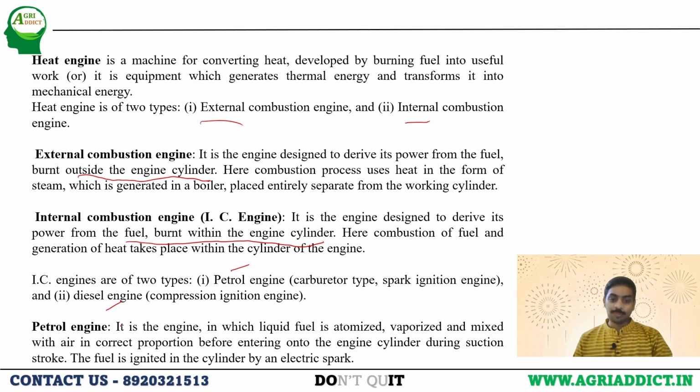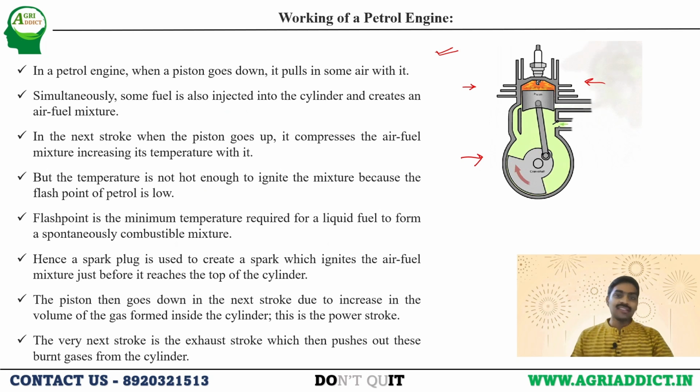And now first talking about the petrol engine. A petrol engine is an engine in which a liquid fuel is atomized, meaning it will be sprayed in the form of particles. It is vaporized and mixed with air in an appropriate ratio, and it will be sent into the engine cylinder for the suction stroke, and later it will be ignited by the electric spark. And this is how the working of the petrol engine takes place.